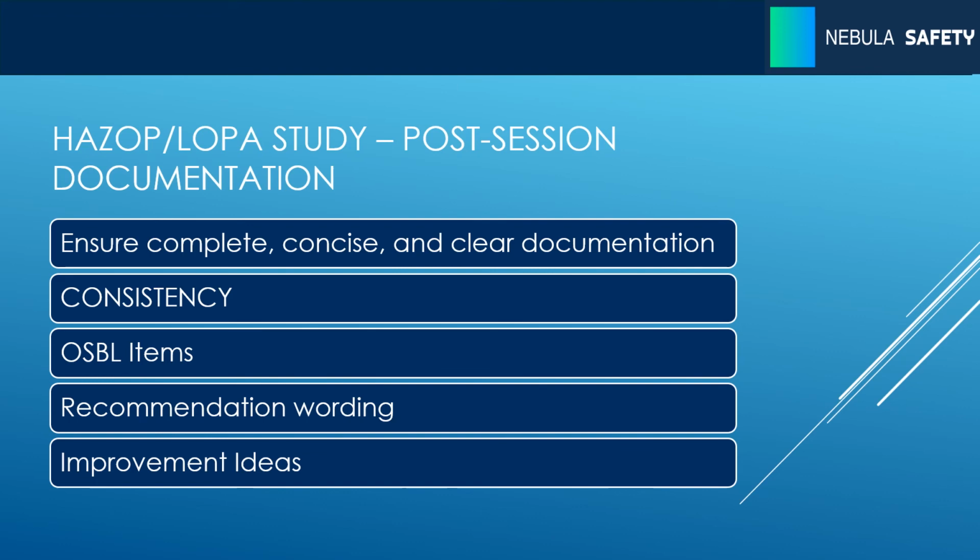A lot of times an initiating cause in one unit will impact a downstream unit, for example, the tank farm, right? We're always sending stuff down to the tanks, and that might not necessarily be the unit we're covering in the PHA. However, we caused it, we own it. So there might not be enough adequate resources available for proper evaluation at the time of the upstream PHA. So a lot of times facilities want to put together a system so we can catch those out of boundary limit scenarios and track them accordingly, to make sure they're evaluated in the future downstream unit PHA.